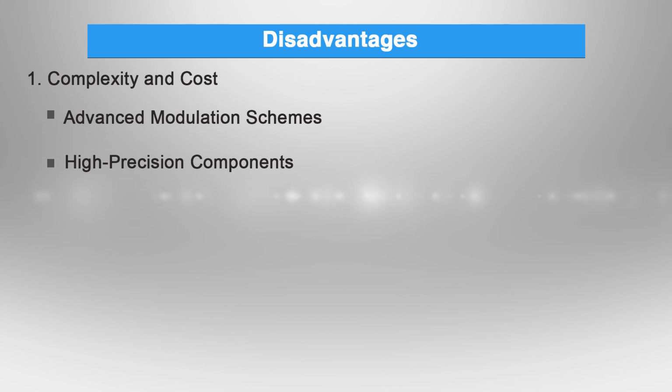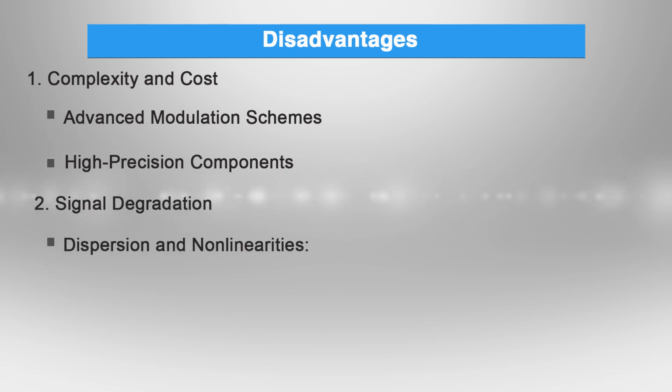Next is signal degradation, dispersion and nonlinearities. Optical signals can suffer from dispersion, both chromatic and polarization mode, and nonlinear effects like four-wave mixing and self-phase modulation.